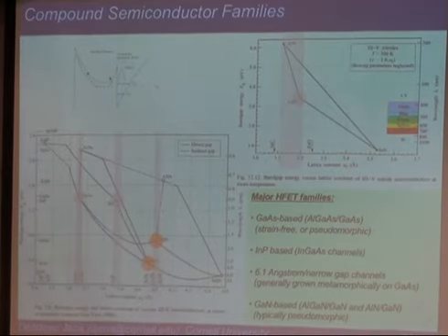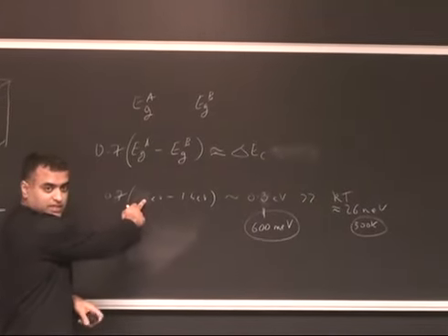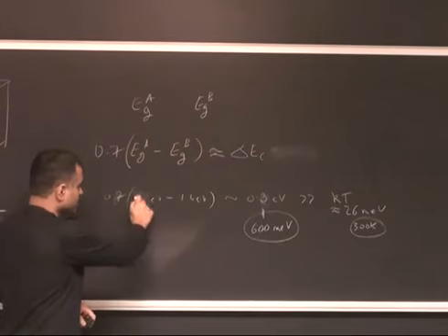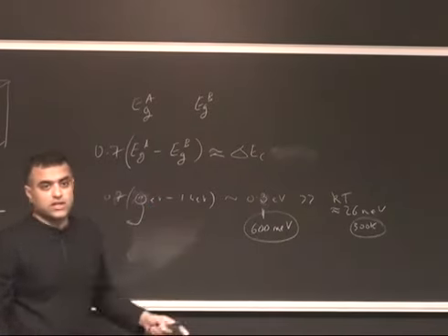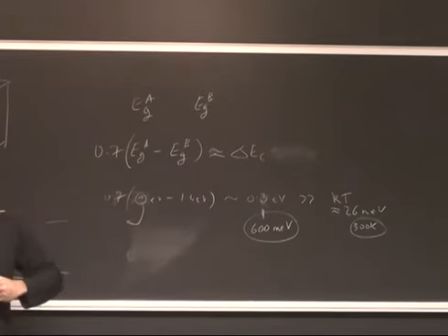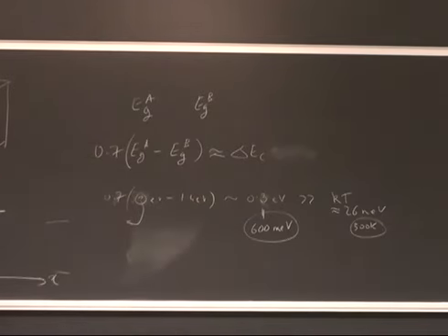But let's say you're designing and you want 0.3 electron volt, 300 meV barrier height for whatever reason. Then you can obviously back out what this should be, right? And then from here, you can choose what composition of aluminum you should use, and you go and actually grow that structure chemically. So that's the design back and forth one goes through here.